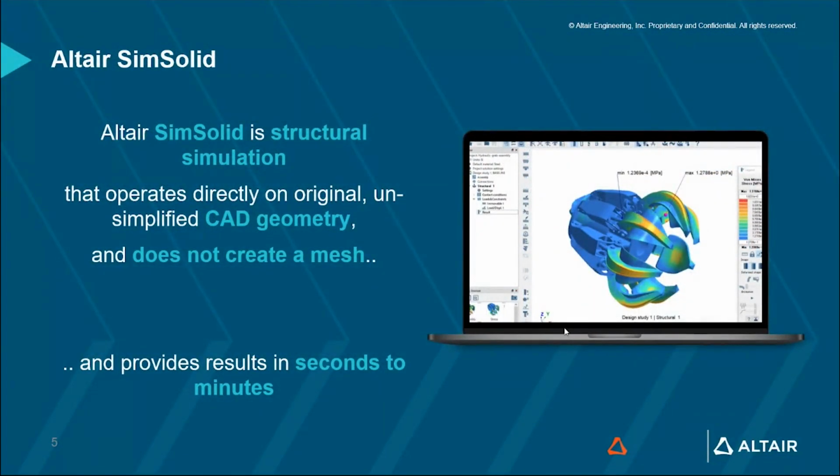Right. What we're talking about today is SimSolid. It is a structural simulation that operates directly on original unsimplified CAD geometry and does not create a mesh. As we know, those are two key important points: typical finite element analysis processes involve tremendously tedious pre-processing in terms of simplifying geometry and creating the mesh. The other benefit with SimSolid is results in seconds to minutes, even with large assemblies. And we're talking large assemblies, 3,000 parts plus.